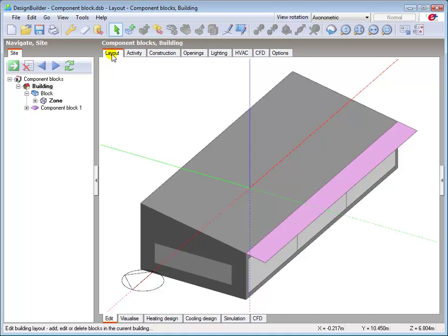An adjacent condition represents the physical properties on the other side of a surface which impact on the heat transfer through that surface. Designbuilder automatically calculates adjacencies between blocks and zones, and the default settings can be overridden at surface level by data entry if desired. The mechanisms for changing adjacent conditions in this way will be introduced in later tutorials. This tutorial will concentrate on drawing the geometric objects which enable the adjacencies to be automatically set correctly.